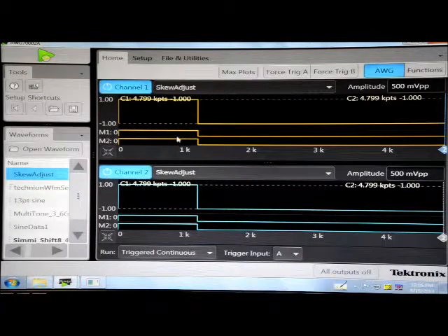You can see that we're also showing the markers here that we use for our sampling scope. We have both channels set up with the same signal. In this case, we can provide this skew adjustment signal. It's a fairly basic pattern. And we have loaded that waveform into both channel 1 and channel 2.